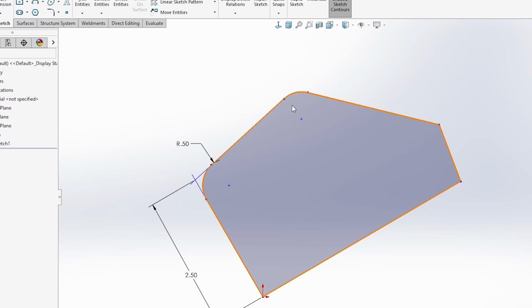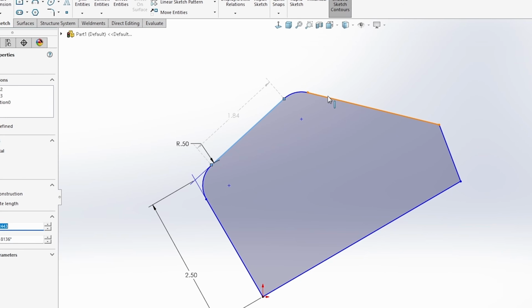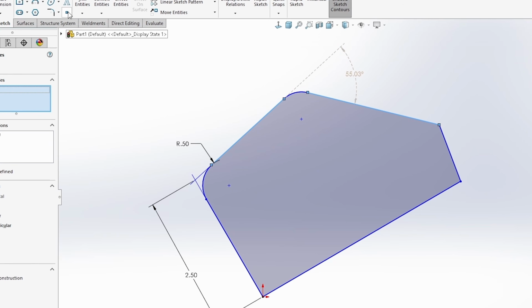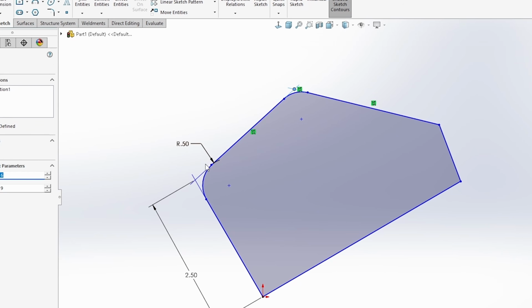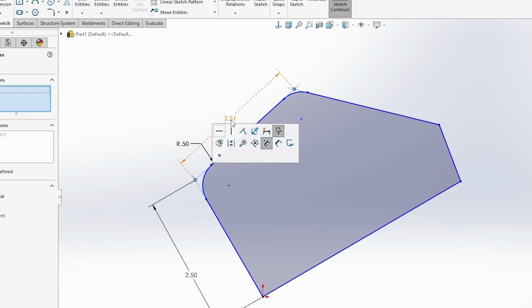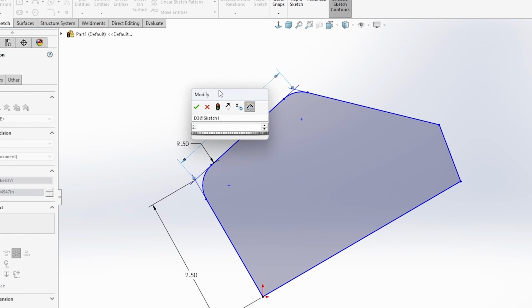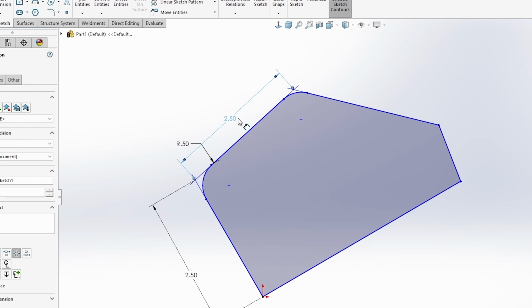An alternative method is doing a multi-select and then using the point tool with those two lines selected, and that'll drop it in for us. And from here we can select this and this, and again maybe we want 2.5 inches, so we've got that all ready to go.